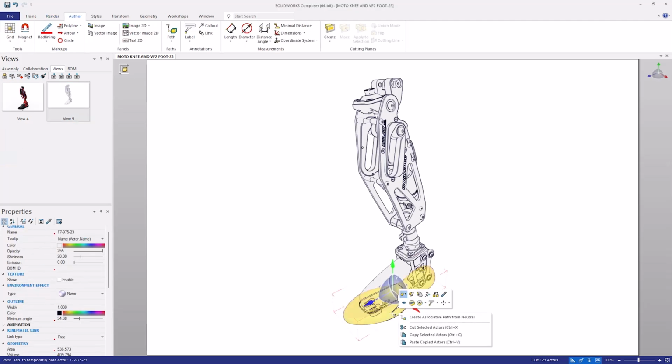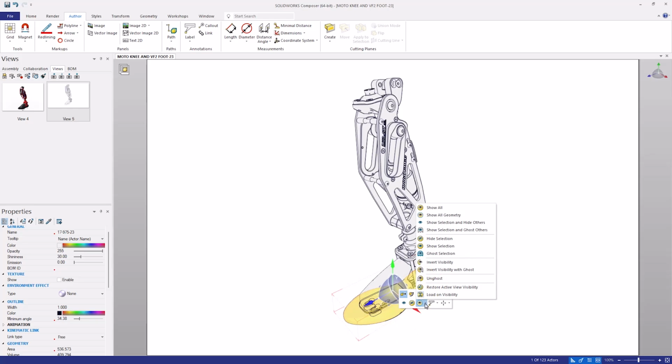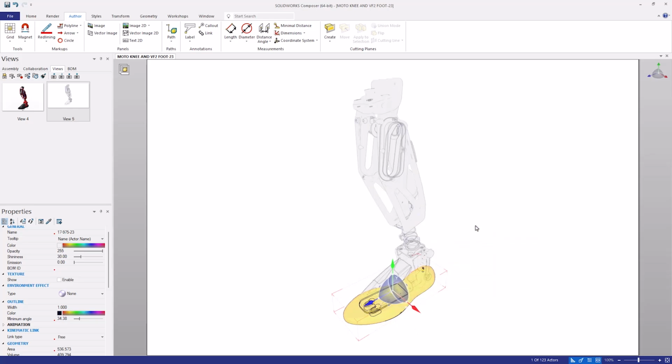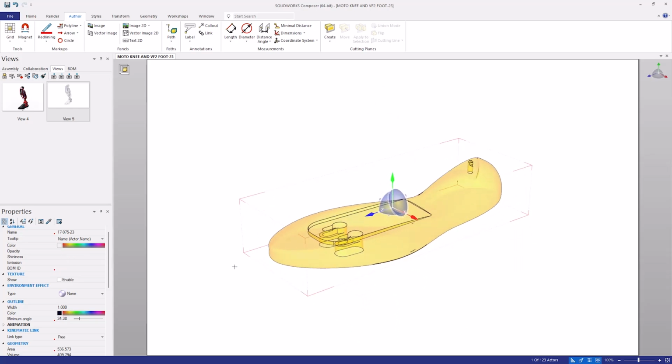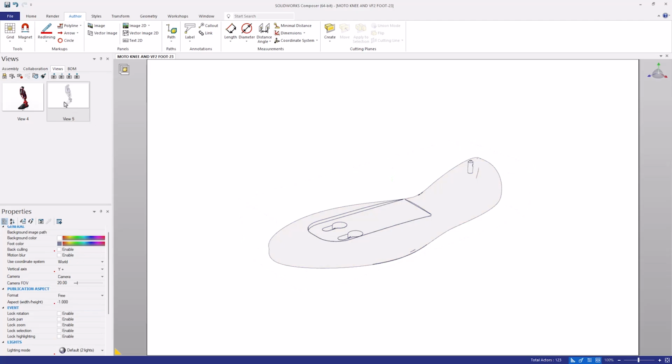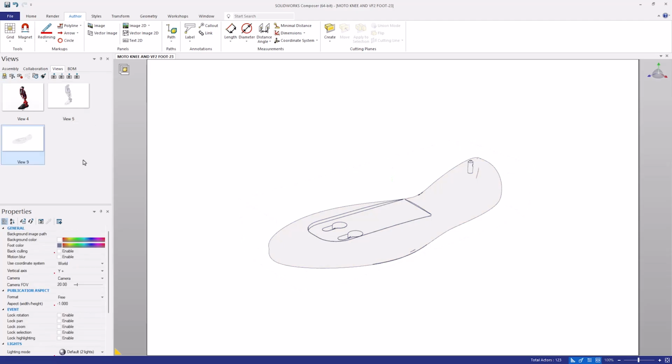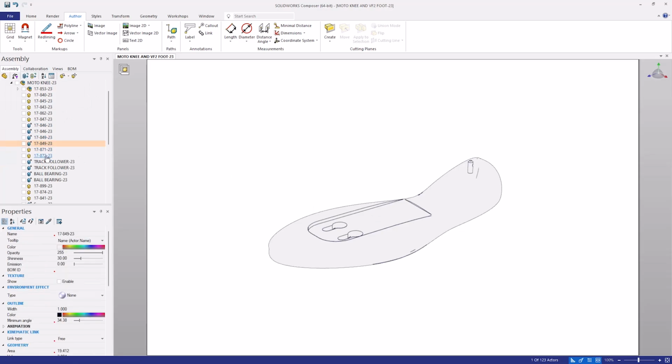Now this is my big tip or work method. Generally you want to build assembly instructions and you might be tempted to do the obvious, and that is hide all the components apart from the first couple and create an assembly step view. Show some more components and then create another assembly step view, effectively building the product up from the ground up.